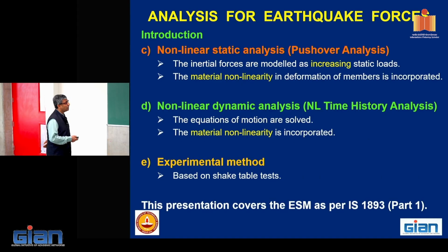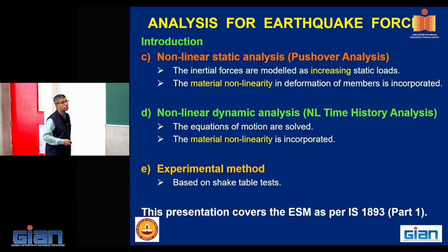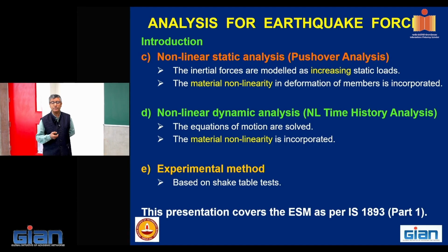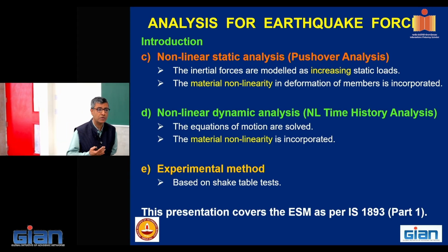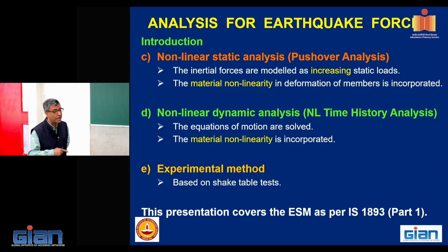If you're going for the nonlinear behavior of the materials in our analysis itself, then that method in a static form is called the pushover analysis. This is becoming more and more common even among practicing engineers, because you can have a more economical design if you are going for a pushover analysis, provided we justify with the connections. Okay.